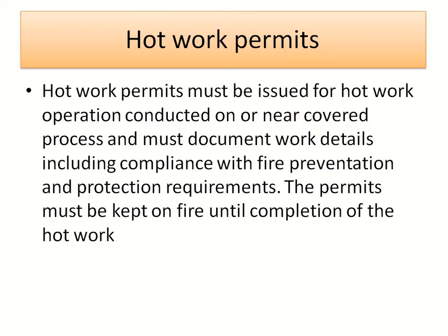Hot work permits. Most industries require permission for hot work. The permit is issued for hot work operations conducted on or near a covered process, and must document work details, including compliance with fire prevention and protection requirements. The permit must be kept on file until completion of the hot work.